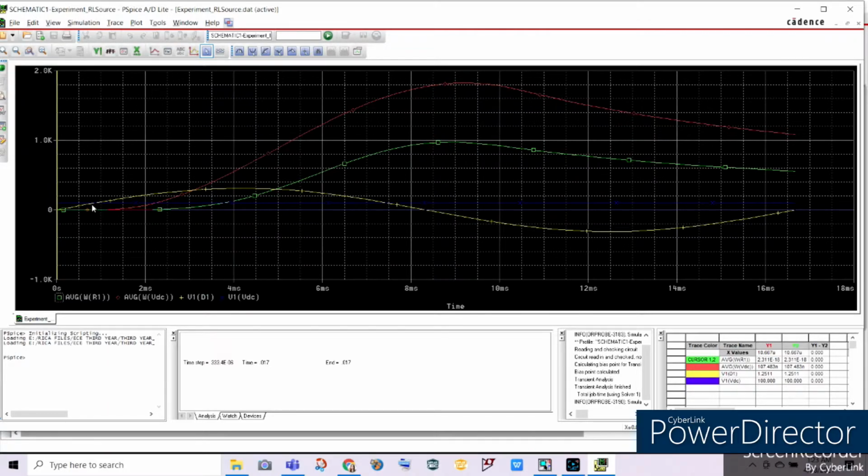But when the voltage across our diode, or the AC source voltage, starts to be greater than the voltage from our DC source, there is a significant rise in our power output waveforms here, meaning the circuit starts conducting and the diode has been turned on. In basic terms, the switch is turned on, so there is a current flow, and when there is a current flow through the components of the circuit, there will be power across our loads, across our resistor and across our voltage DC source. So that's the logic behind that.